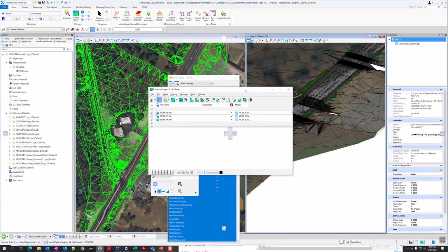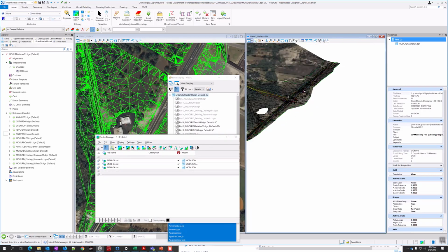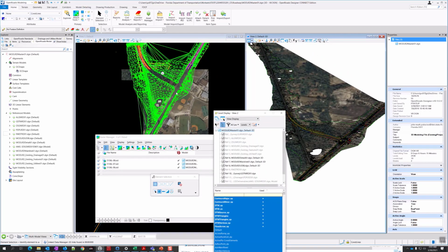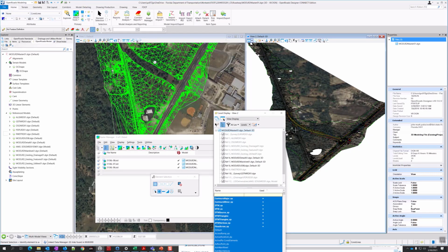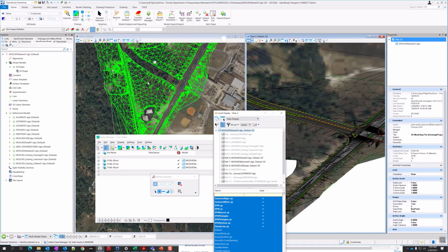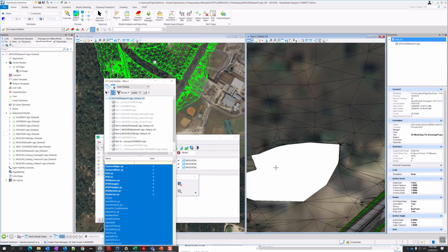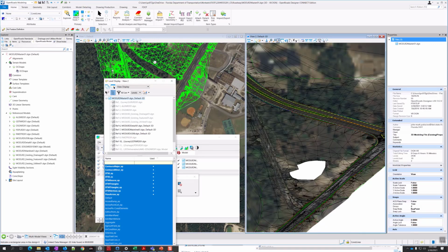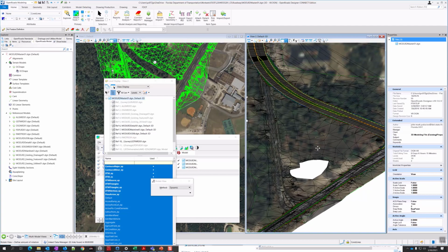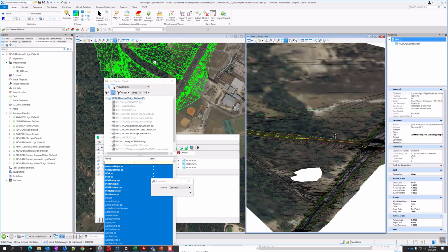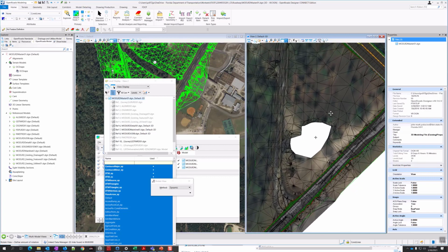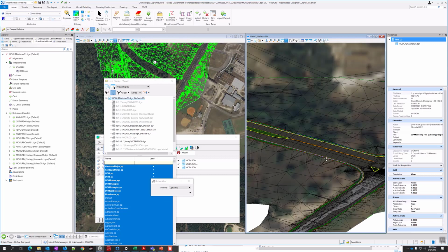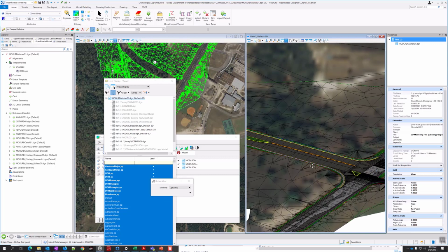It should bring it in both views. Yeah, it's just taking a second longer than this 3D. So it's got to load up all the aerials now. So we see the aerials in the 2D. Those are just 2D aerials, but in your 3D view, these are draped on top of the existing ground. So notice wherever the existing ground doesn't go, there's a hole here. There's no aerials there. If I rotate this, the aerial, as you can see, is attached to the triangle, so it rotates with it. So it's a little prettier than that ugly green. It gives you a sense of your existing features.